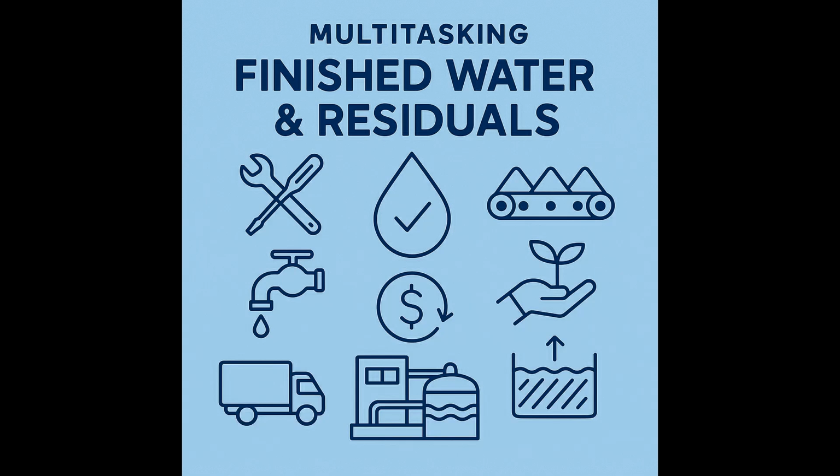Second is the thickening process. How does the plant reduce the water content in the sludge before final dewatering or disposal? They might use gravity thickeners, dissolved air flotation, DAF, or gravity belt thickeners. And the benefit there is less water to haul away, right? Yeah. Exactly. Lower hauling volume means fewer trucks, lower transport costs. And thickened sludge can sometimes be more stable. But the flip side is the cost of that thickening equipment, the energy it uses, and often more polymer chemicals.